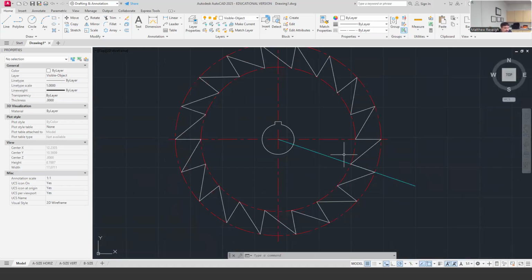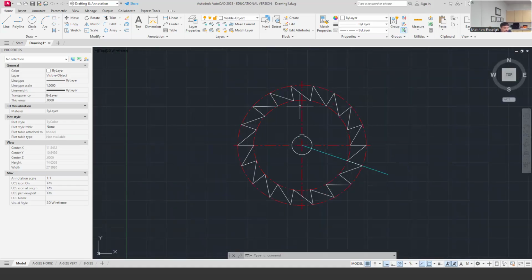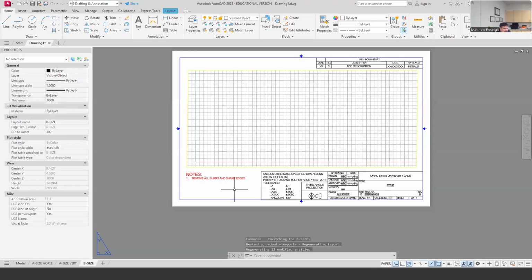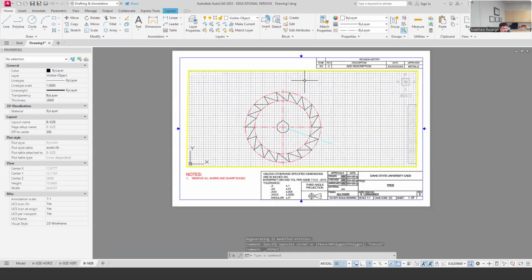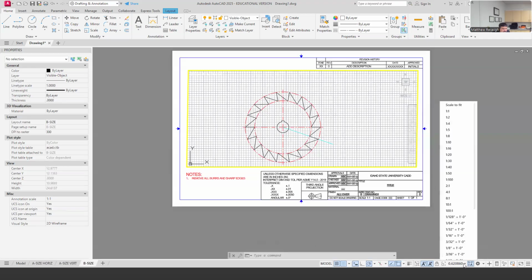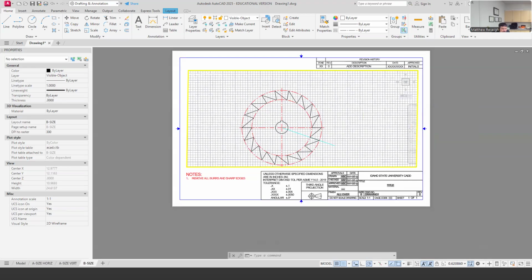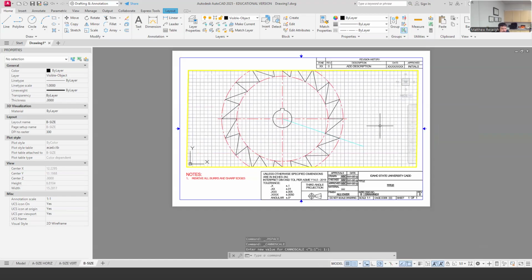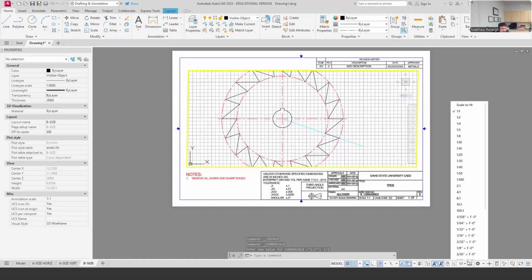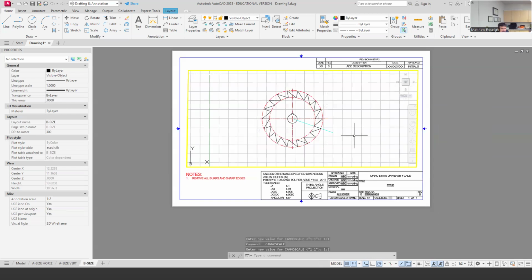Okay, so I just wanted to mention this. This thing is done, I think. So I'm ready to take a look and see what this looks like. Maybe on my B size sheet, I'll zoom in and find it here, get an idea of what it looks like. I think I'm at 1:1 on my B size sheets. It's probably not going to quite fit. Half scale is probably going to look really small. I'm probably going to want something in between a half and a 1, like 3/4 scale. So if I use a B size sheet, I feel like I'm going to make a custom scale.